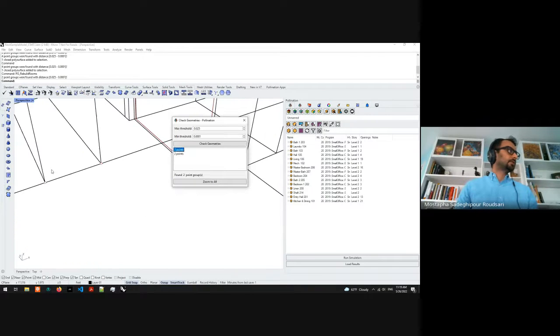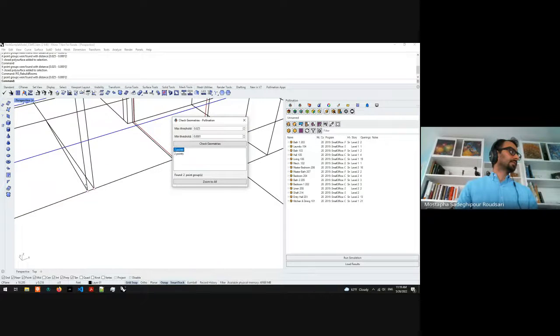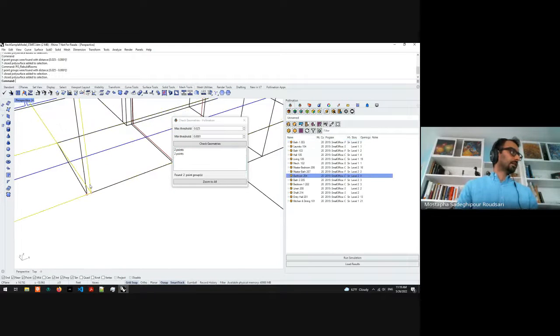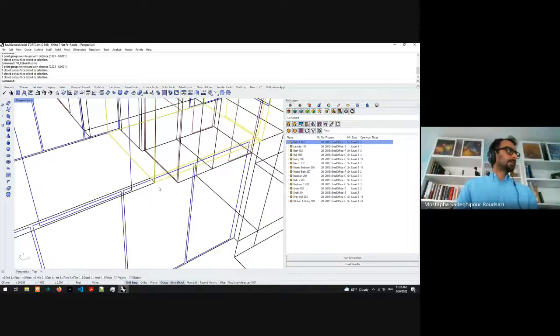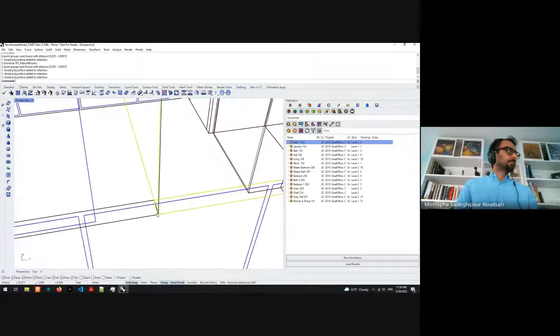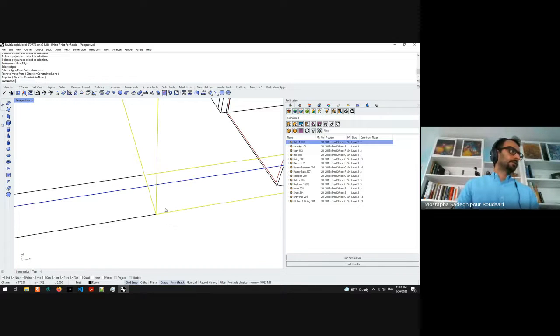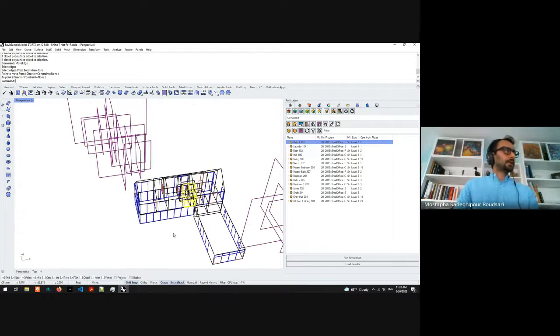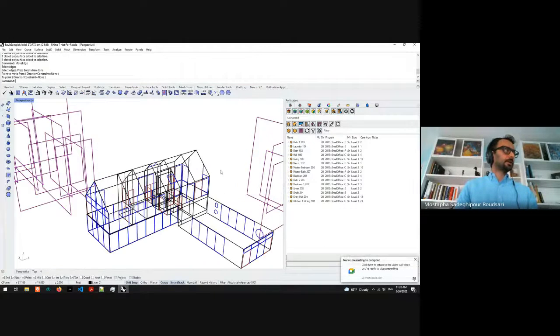So I still have one issue here. So let's look at this one. It looks like we have this room inside the other room. This one, my bath, the way it's modeled, it's not modeled correctly, so it's coming a little bit inside this, and that's causing an issue. So I can do move edge, and I'm moving this from here to here. So what happened is I fixed those two issues that we just talked about, and that interface updated live.